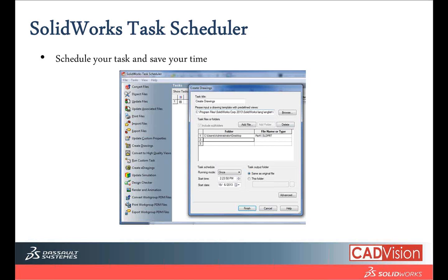The next will be SolidWorks Task Scheduler. Not many people know about this, but you can schedule your tasks to save your time. Let's say I have all my products ready with all the proper dimensioning and proper relations. If I would like to create drawings from all these particular part files, we can schedule a task in SolidWorks Task Scheduler. You can look for this in the Start menu. Just go to Start, go to Program Files, go to SolidWorks. Under the SolidWorks tools, you can search for your SolidWorks Task Scheduler. Here, you can simply click on Create Drawing, and select the files where all your parts are stored. I want to run the model once.